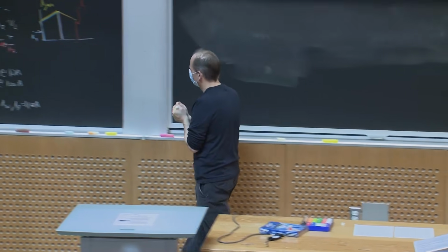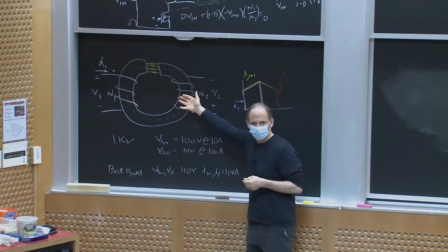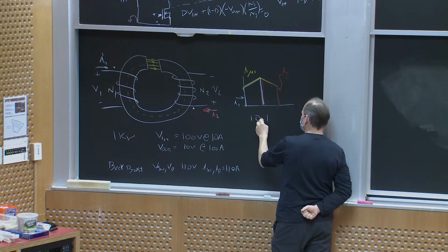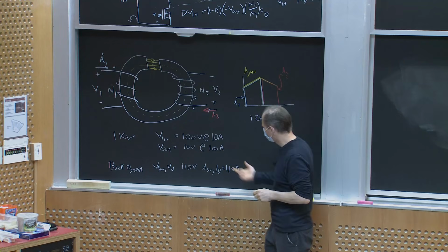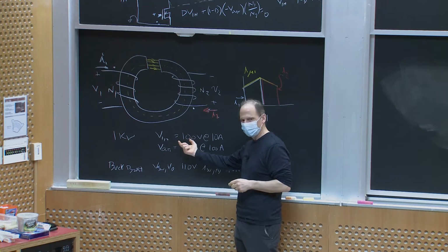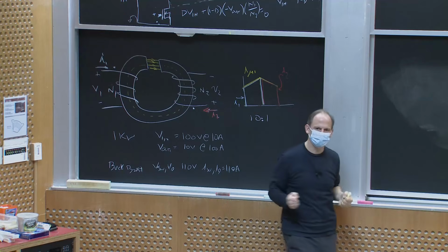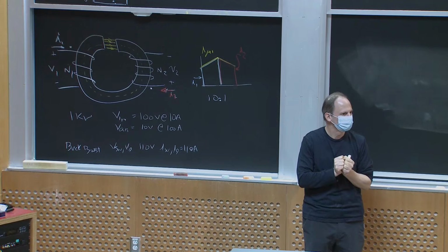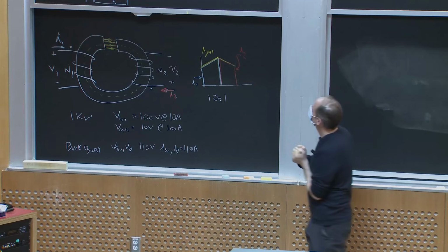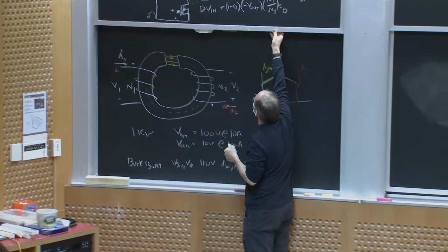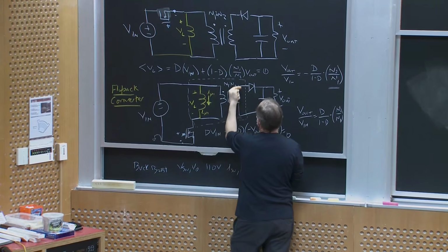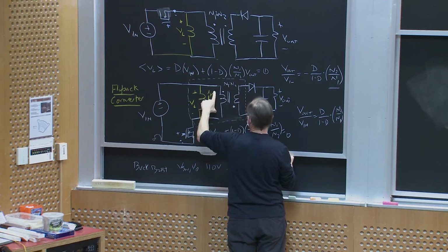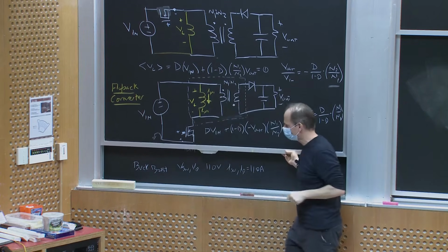On the other hand, suppose I designed a flyback and I used a 10-to-1 transformer. So I'm going to get my scaling, instead of just by using some extreme duty ratio, by putting it into the turns ratio. What does the turns ratio do? That rescales the high current seen at the secondary to the low current at the primary, and the high voltage at the primary seen as a low voltage at the secondary.